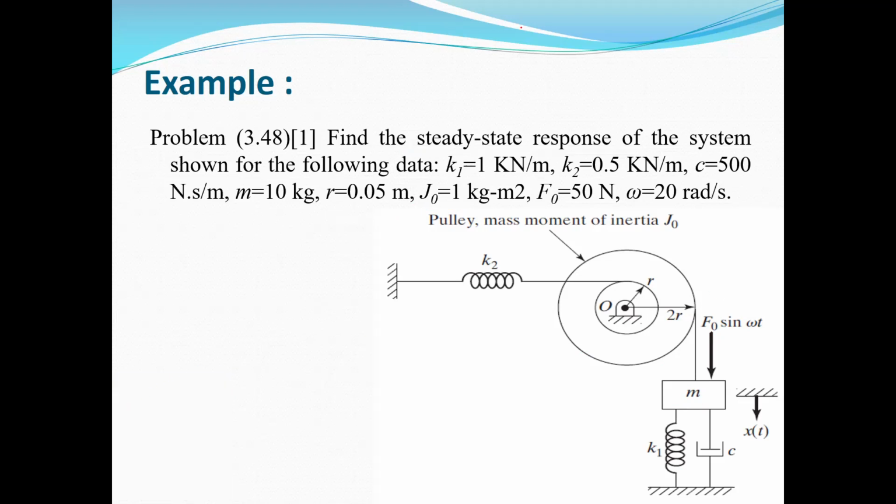To find the equation of motion, the main important question is to obtain the degree of freedom, because according to the number of degrees of freedom, we will find the equation of motion. For example, here, if we assume this is a 2 degree of freedom system, the equation of motion will include 2 equations, or it will be a system of 2 ordinary differential equations. But definitely it will be a single degree of freedom because we are discussing the SDOF systems.